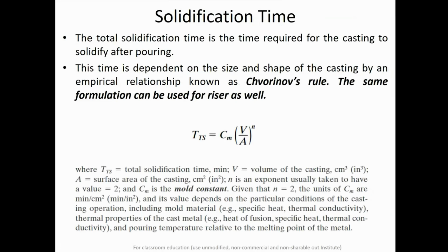Solidification time. The total solidification time is the time which is required for the casting to solidify after pouring. And this particular time obviously depends upon the size and shape of the casting. There was a scientist whose name was Chvorinov.